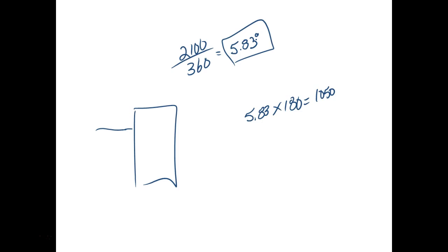So the speed of the pulses would tell me the what? The speed. Which one leads and which one lags would tell me the direction, and then the number of counts would tell me the actual position. So these are quadrature encoders. This is a servo motor. It means it provides feedback. There's three things a motor could give me: speed, position, or direction, right?